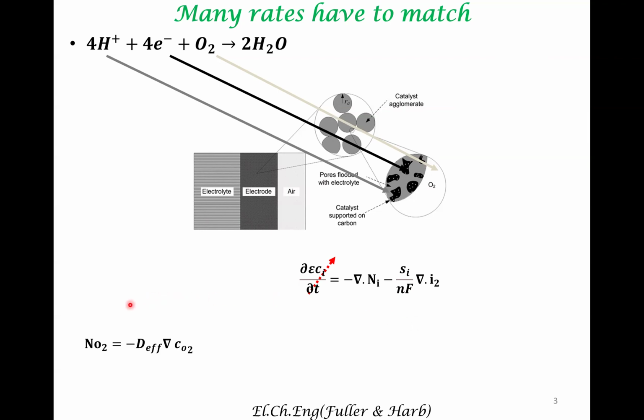So the flux which we are talking about is the flux that is transported across a particle. Let's say you are thinking about O2. O2 concentration can be fixed at, let's say, the particle surface, but this O2 gets absorbed into this catalyst particle, and there can be a gradient in concentration of O2 inside the catalyst particle.